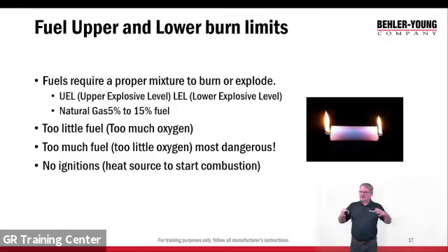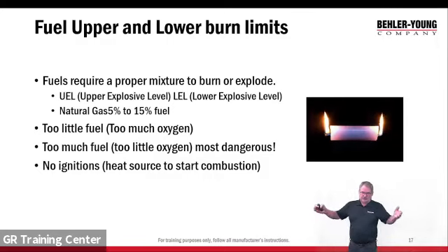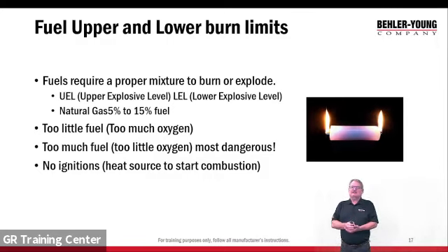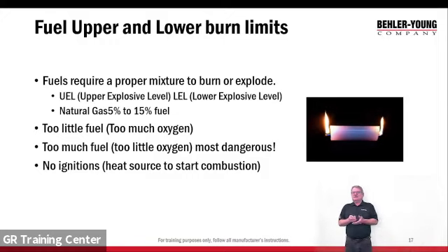So picture a room, whatever room you're in. If you have some natural gas leaking into that room, you can smell it. And you had some type of meter to read that, and you are at 3%. All right, there's 3% natural gas in the room you're in. It won't ignite. It's below the lower explosive level limit. So as the leak continues and we get to that 5% in the air, so again, 5% of the air in the room you're in is natural gas, and you hit a light switch that sparks and we can ignite it. It can burn.